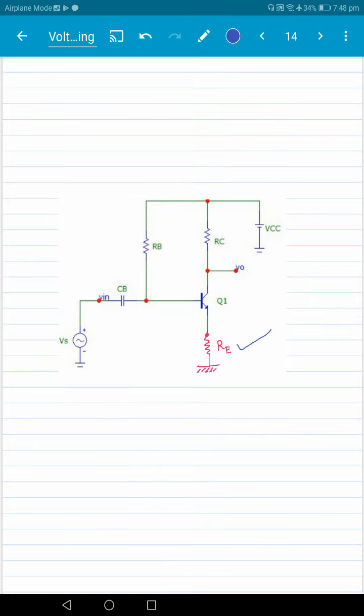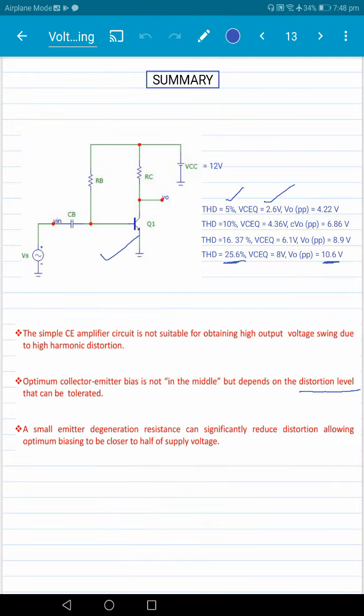But coming back, since we are talking about voltage amplifiers, in voltage amplifiers there would always be this distortion here. The relationship between IC versus VBE, the base emitter voltage, is an exponential relationship, and that's the source of nonlinearity.